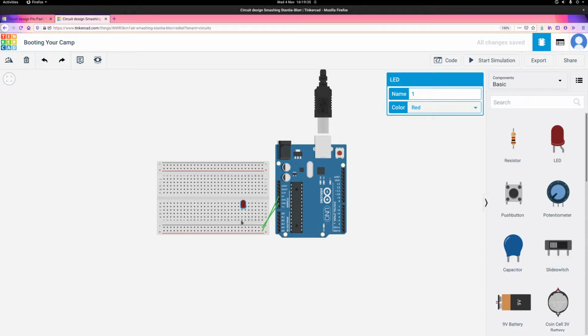But if we were to connect it, say, in a different way, like this, then we would have an issue, because now the negative and the positive are connected directly together, so you're kind of shorting out that component. So it wouldn't turn on. Wonderful. All right, so I agree. 2 different rows is a good idea. I'll put it way up at the top so we have plenty of room.